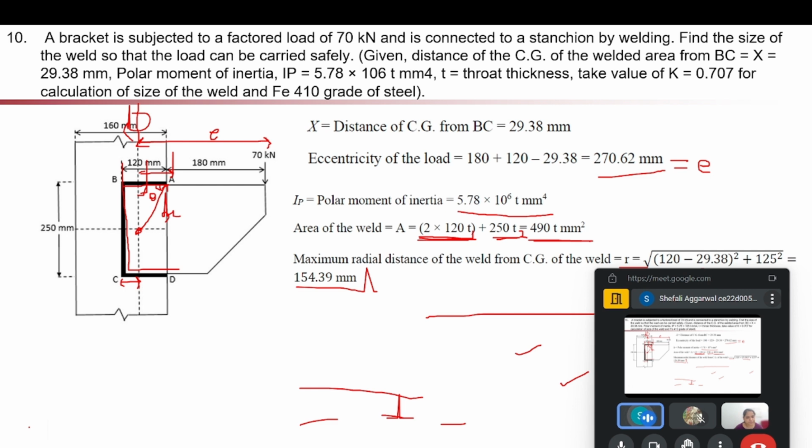There we are looking at the failure pattern, where the possible failure can be. They were calculating the bolt strength and tried bolt bearing failure and shear failure, and they considered the least one for the criteria.